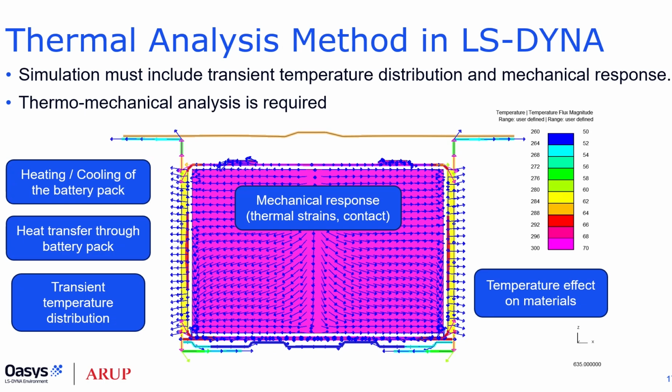We want to predict the mechanical response of the materials in the pack in order to predict damage due to thermal expansion and contraction. And importantly, we may need to consider the effects of temperature on the material properties themselves, such as their Young's modulus or yield stress. Because of all these requirements, we need a coupled thermomechanical solution, which of course we can do in LS-DYNA.